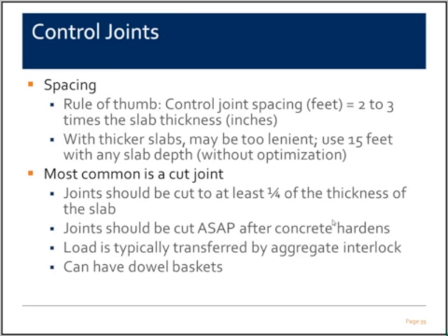With thicker slabs, and this is my experience and my opinion, we should probably keep that joint spacing at 15 feet. And this is based on my experience, and without any optimization of the design, I think we need to keep to that. The most common control joint that we see is a saw cut joint.